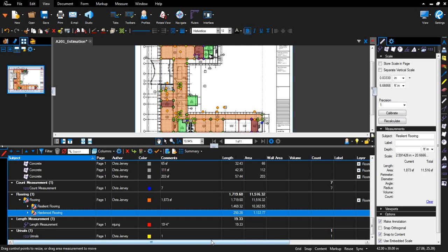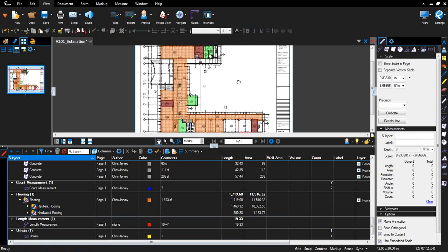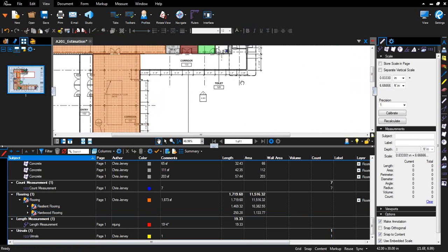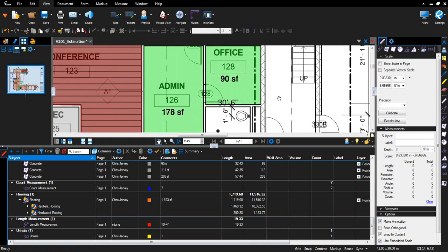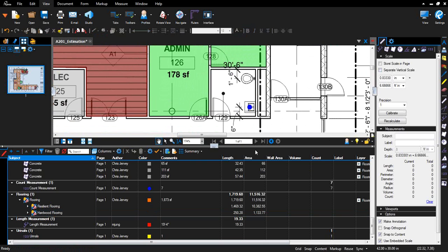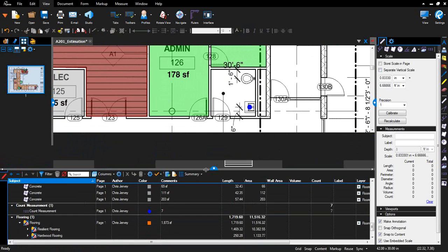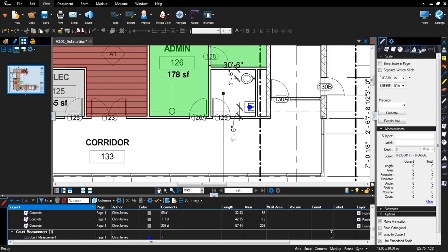Okay. Now, the radius tools, one of the other great new tools for measurements, is the ability to do a center out radius. Previously in Revu, when doing radiuses, your option would actually be a 3-point radius. But now with a center radius, for example, people looking to see if this is ADA compliant can measure out 2 feet 6 inches, 2 feet 5 inches. We're pretty close. Looks like that bathroom will pass ADA compliance over here.